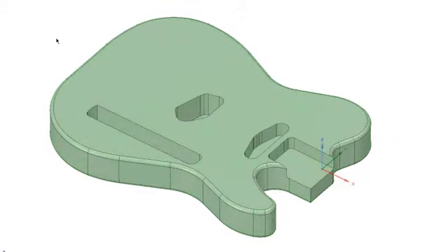From the scanning perspective, it's the combined accuracy of the arm and the laser line probe, and typically you're looking at about plus or minus 3 thou.